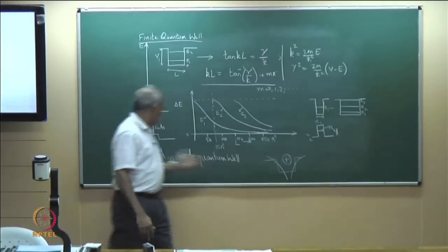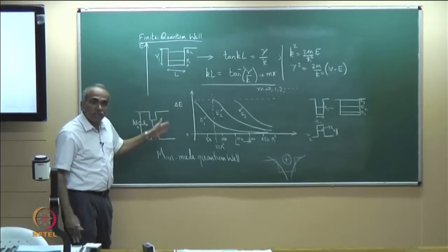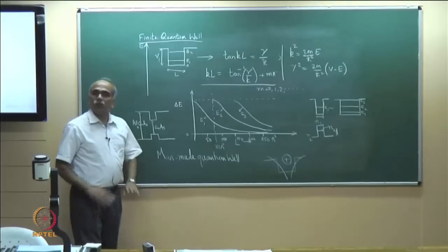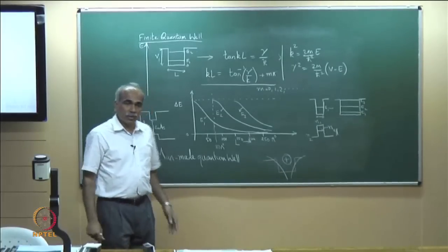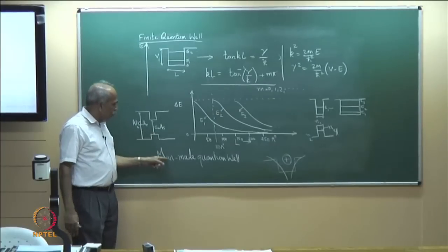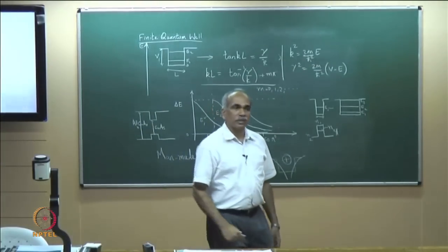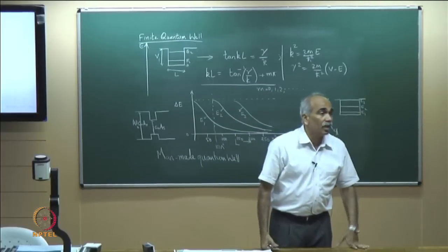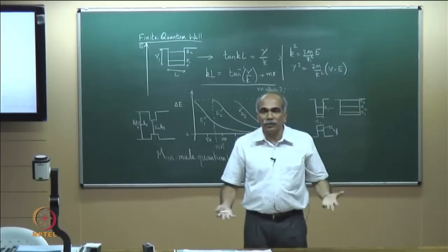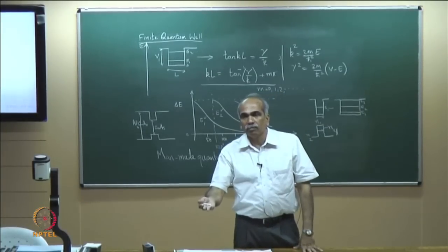Today, this is a real problem, and you have a real particle in a box. This box is real now. It is no more a hypothetical approximation, because these structures are real heterostructures, hence the name man-made quantum wells. You can grow double heterostructures and you can realize quantum wells where the original results of particle in a box, which we used to study in quantum mechanics, are almost directly applicable.